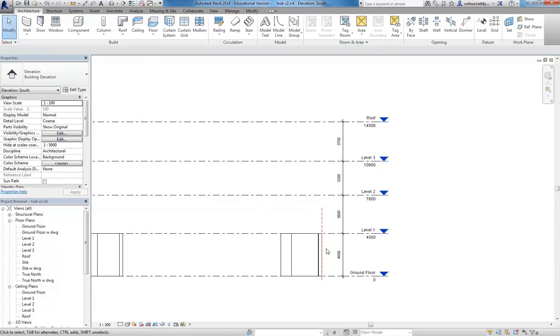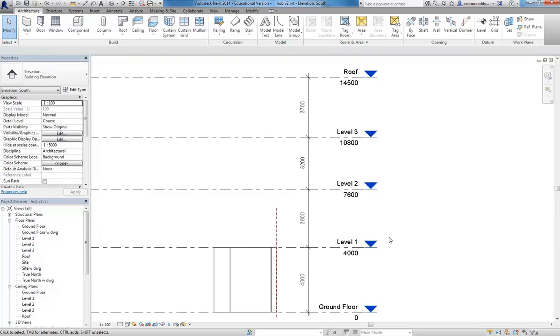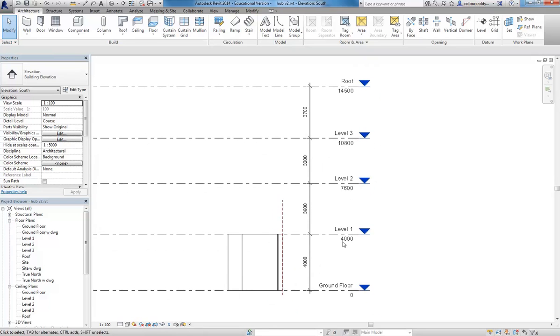But one of the huge advantages you have with Revit over every other BIM program like ArchiCAD or those others is that it's a true BIM program. It's parametric all the way through. And simply what that means is you can change the levels later and all your objects will update automatically. So if I realise later that these levels need to move up or down a metre or two, it doesn't matter. Everything on those levels will stretch accordingly and then connect to the level above or below as it should.